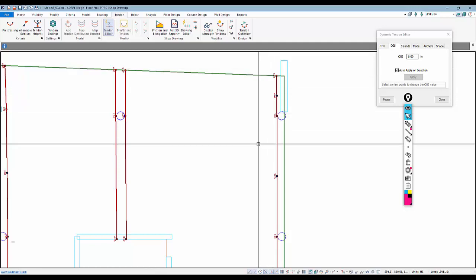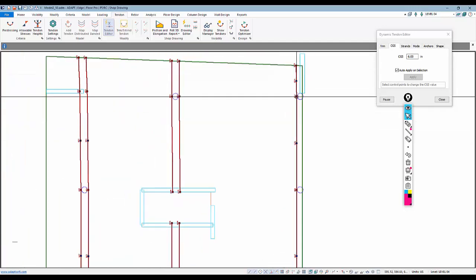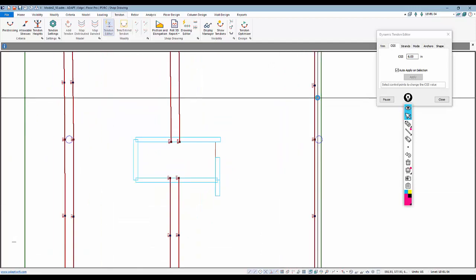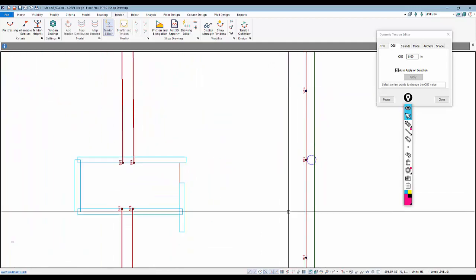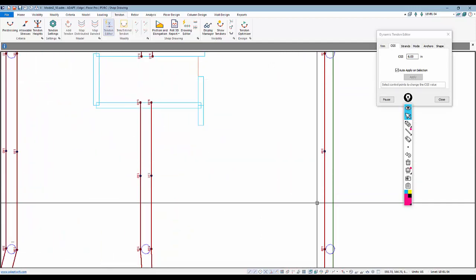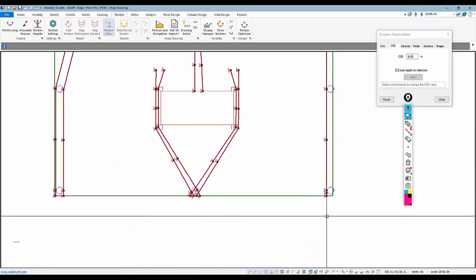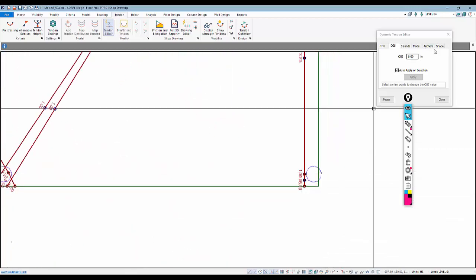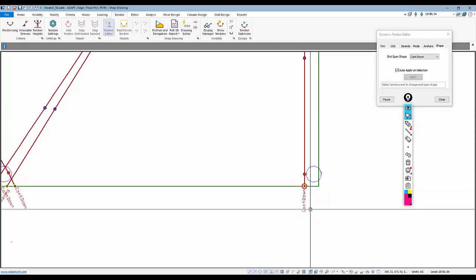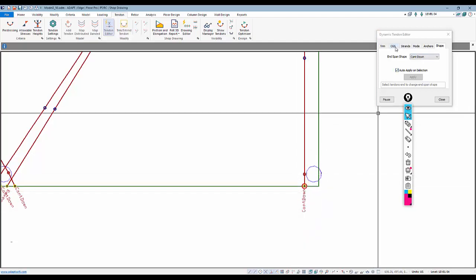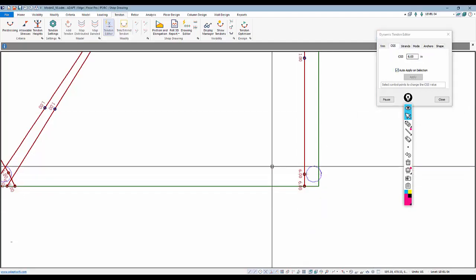That will run straight down to the CG from a high point here at this first column. This low point is 3.25. The program had lifted that up to maintain the balancing. And then again, we have a situation here where we want to cantilever down because of that short span, and I'll change the CG to 6 again.